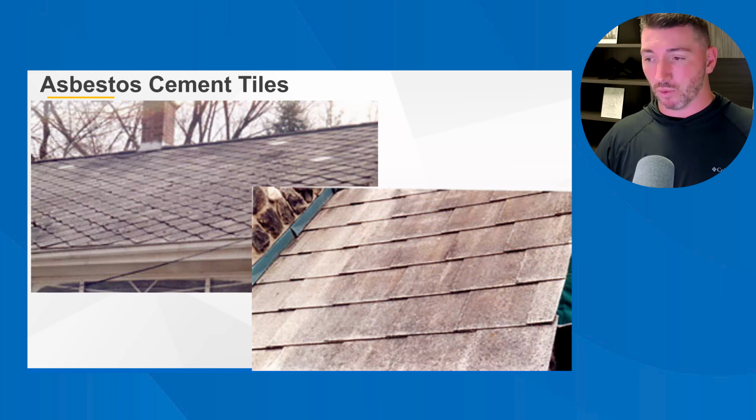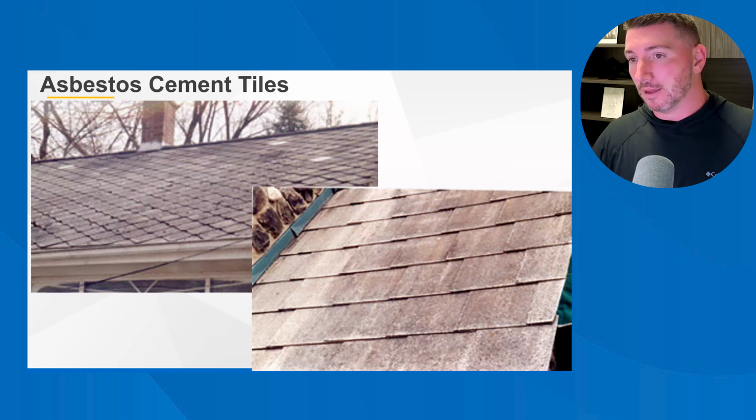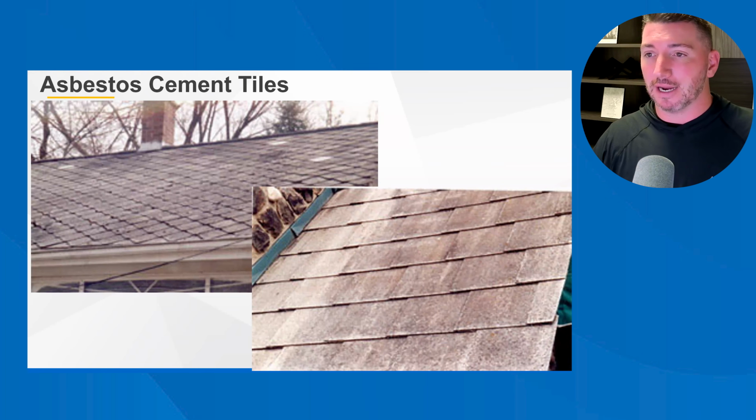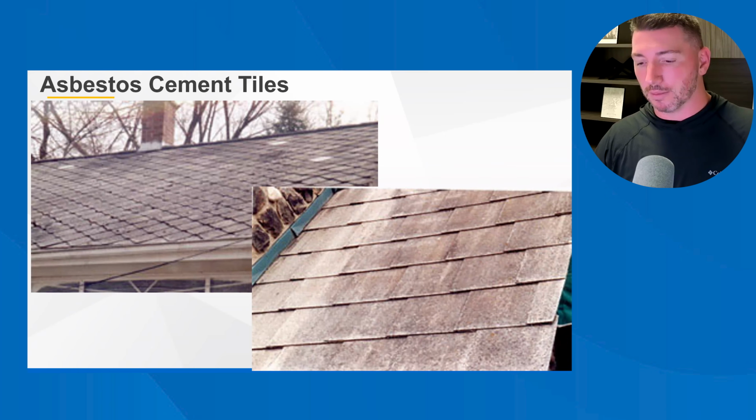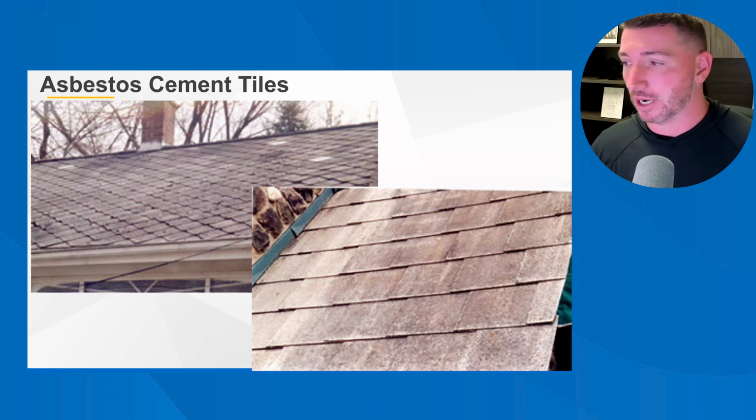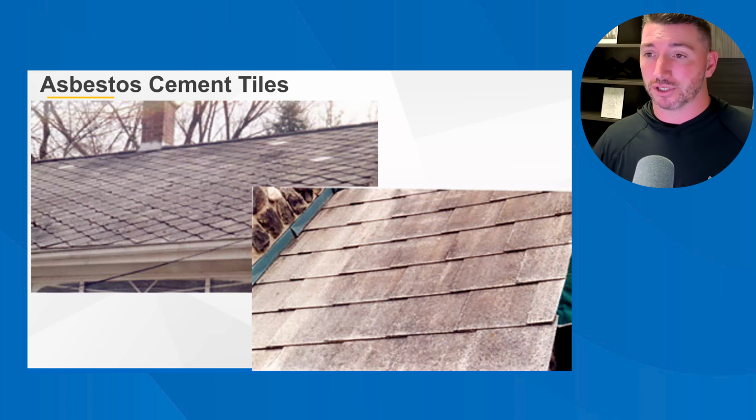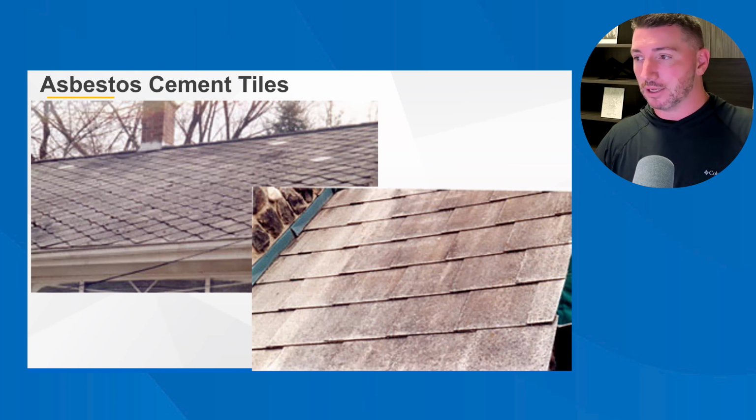Those diamond-shaped ones are usually asbestos. You can call it out by design if you're confident to do so. Otherwise, you recommend having it tested. And at that point, if there's a roof issue, there's a special process. Again, I participated in a job where they quoted $90,000 just to remove the roof. That was before the new roof went back on. $90,000 for, I think, a 50 or 60 square roof, just for the mitigation team to come in, suit up in hazmat suits, and properly dispose of the asbestos.